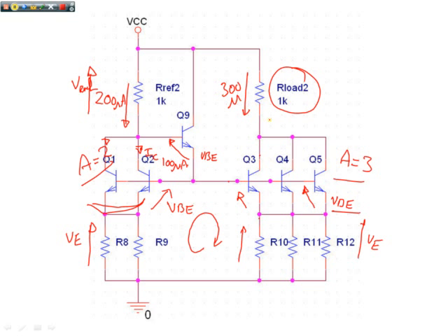So the spec says the output current is 300 micro. As the output current is 300 micro, each BJT is taking, in effect, 100 micro. And as you come down here you see 100 micro. So everybody is taking 100 micro, therefore VBEs can be locked off, therefore REs are exactly the same, which means it's very easy to calculate. That's the kind of process that you might use on an IC. So I'm not going to tell you any more about that circuit, I'll leave it for you.